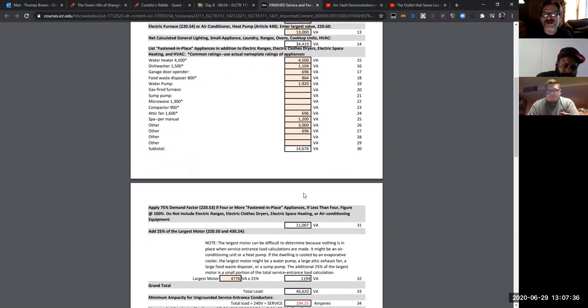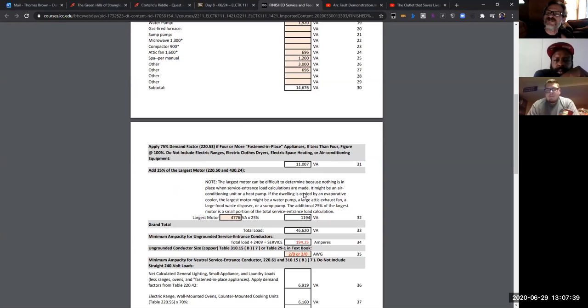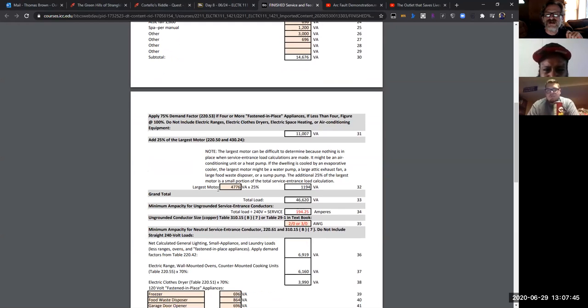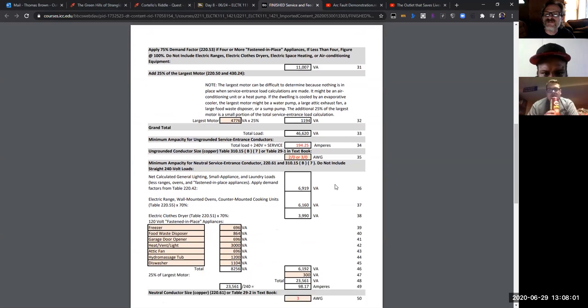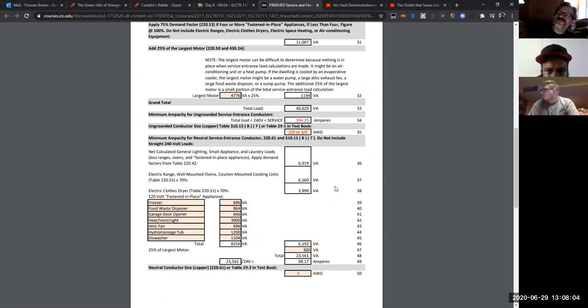What we're trying to do is figure out how much supply my house is going to want. By figuring all these out, and of course, we have the motor factor involved, that's our overall continuous duty. That way we come down to number 34, which tells me what size service I'm going to need. Remember, we're at 100, 150, and 200. If you're in this ballpark, then you're pretty much on track, and you're going to tell me we need a 200 amp service.